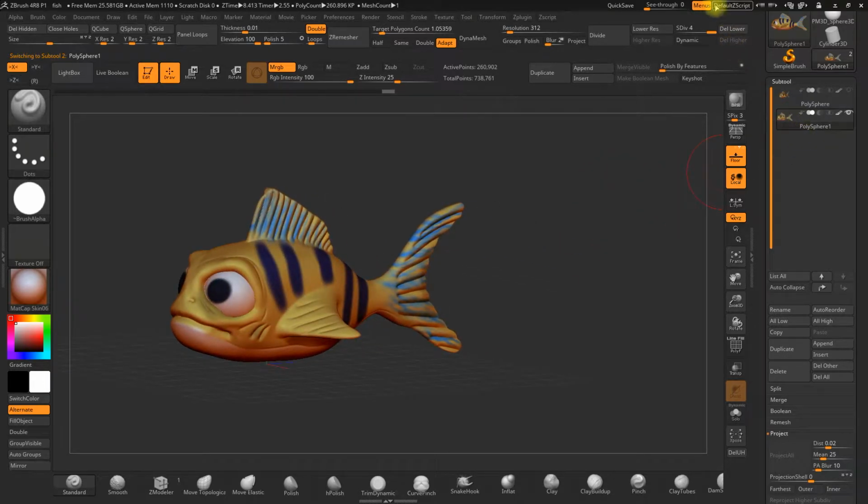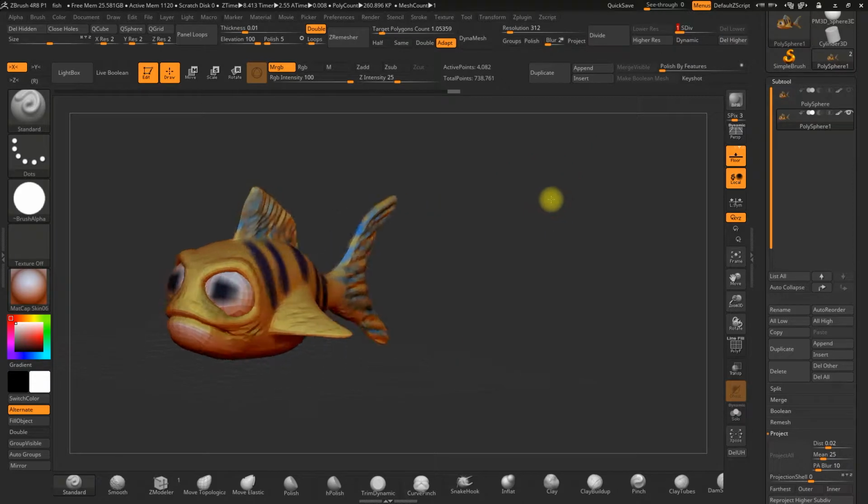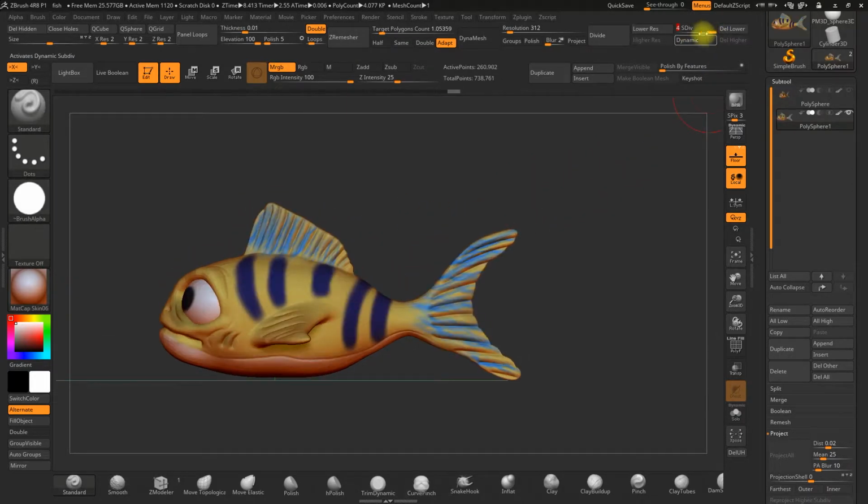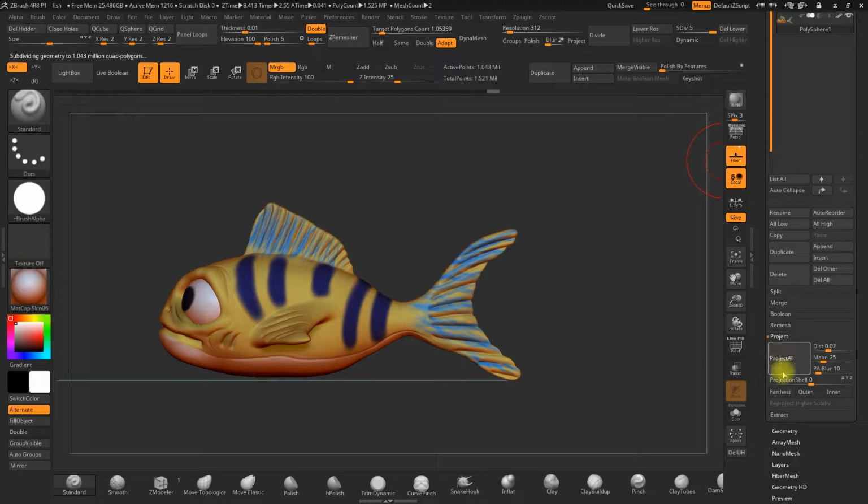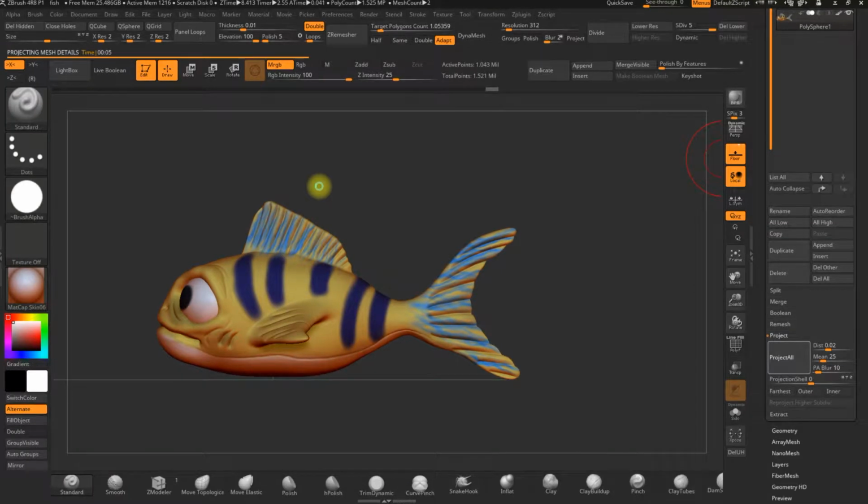We also did something important to get the UV map later, which is the fact that now the low poly model has different, as you see, subdivision levels, which is very important in order to be able to animate it properly. We can even get another subdivision level, activating the high poly version, and click Project All again in order to finish allocating all the polygons and obtain a very precise model.